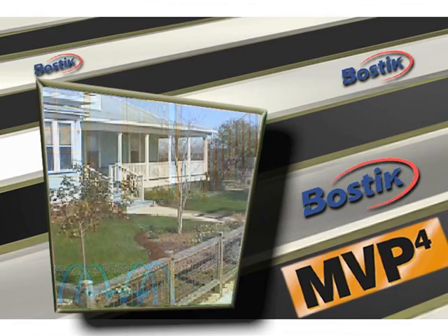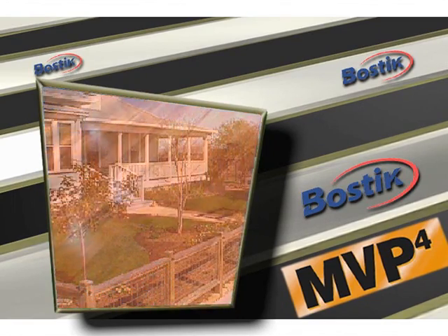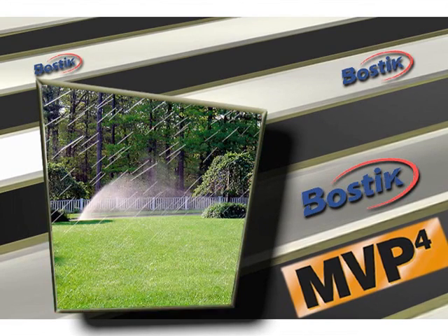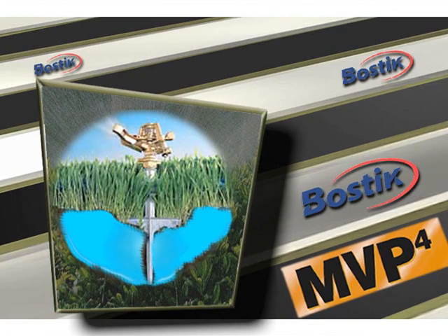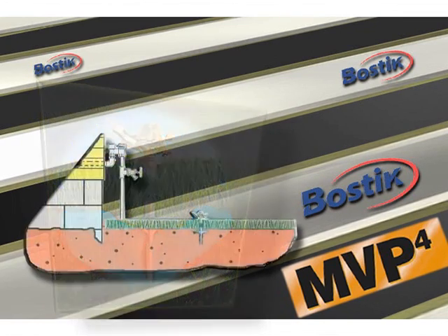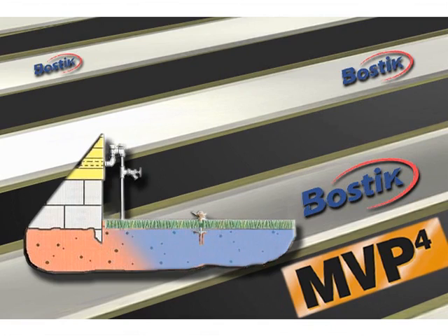For example, a week after our homeowners installed their new wood floor, the automated lawn sprinkler system was completed. What they didn't anticipate was that the sprinkler system was not able to drain properly, and there would be a dramatic increase in the subfloor moisture content down the road. No moisture test would have been able to predict or warn of this future set of circumstances.